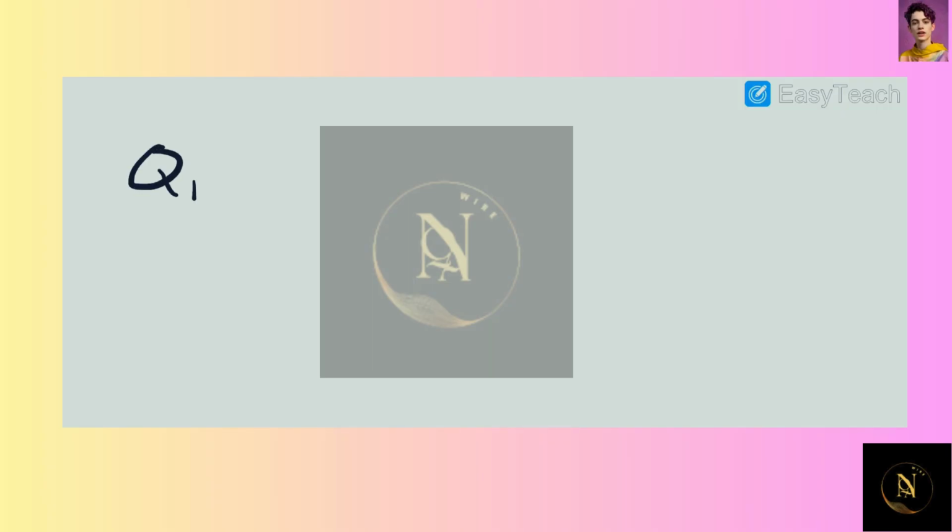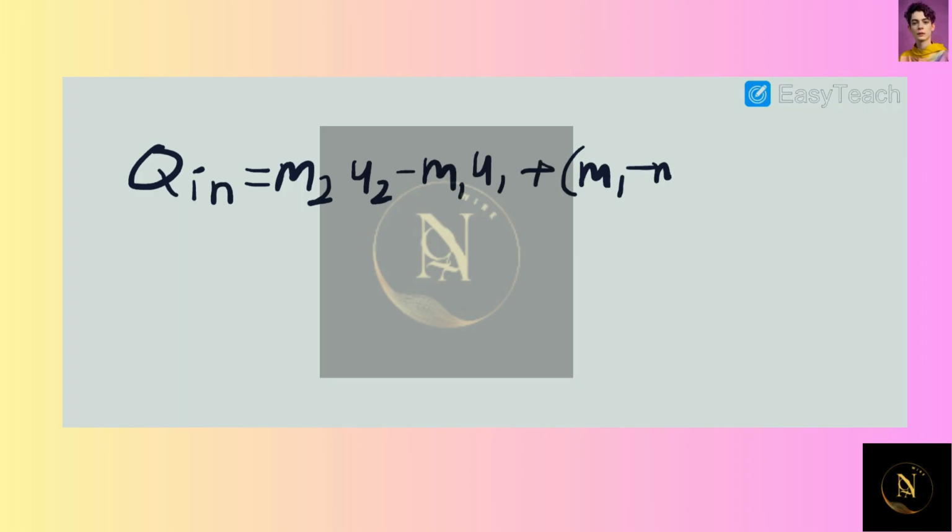Recall that our energy balance equation for Q_in is equal to m_2u_2 minus m_1u_1 plus (m_1 minus m_2) times h_e. So we have all of these quantities. We can go ahead and plug them in, and we get a final Q_in that's equal to 72.8 kilojoules. And this is the heat transfer that's required to maintain constant pressure and constant temperature during this process.